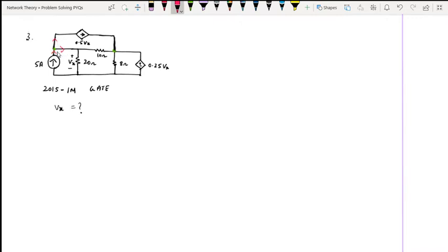All right. So if I see the current, this current is divided here, right? Whatever the current flowing through this 10 ohm resistor and this 20 ohm resistor, the sum of these two currents is the equivalent current here. So at this node, if I write the equation, I can say 5 amperes current is equal to the current that is leaving, that is 0.5 Vx, plus the sum of these two currents, the current to 10 ohm and the current to 20 ohm. Why? Because this is the equivalent current we have to think about.